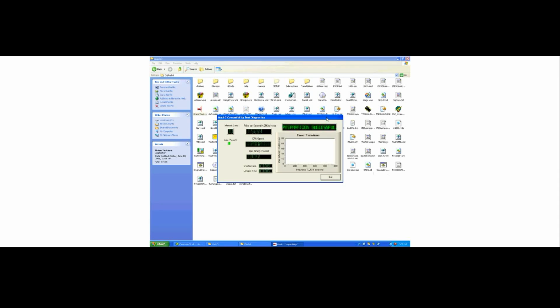If you get a waveform which is terrible, one which is not a straight line like this one gives you, but large spikes all over the system, or you may find you've got noise going up to this level and periodically messing up your waveform, then you need to run a file called optimization.txt. This is a text file which has several steps in it which can help you to remove processes in your computer that Mach3 is having a problem with.